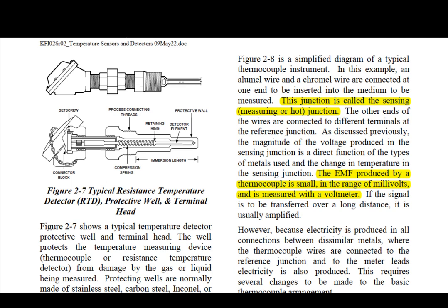Now this is where I want to stop and tell you about the reactor coolant system. In the reactor coolant system, we have a large pipe that comes out of the reactor. It's very, very large, approximately, what was that, 28 inches. That's pretty big for hot, high-energy water coming out of the reactor vessel. And we have 3 thermocouples in that pipe. Each one of them is approximately, was it 270 degrees? It's a Y shape. You have 3 of them.